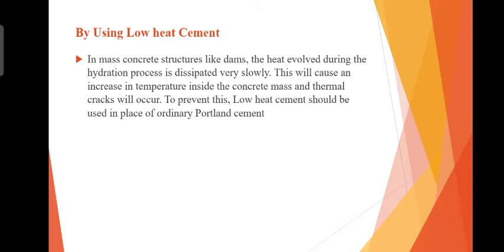In mass concreting structures like dams, heat is involved during the hydration process. We know that when cement mixes with water, a hydration process starts, and the heat dissipates very slowly, causing an increase of temperature inside the concrete, and thermal cracks will occur.